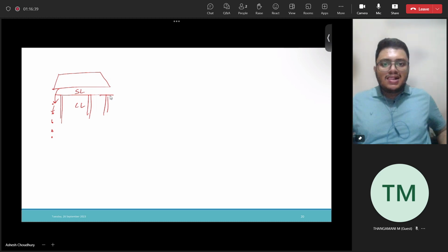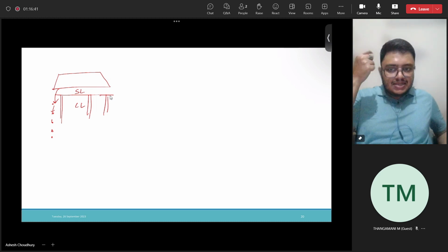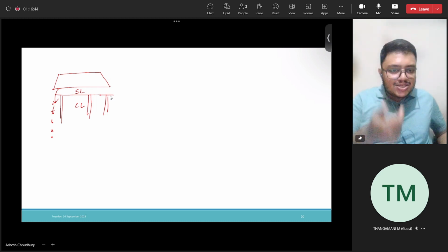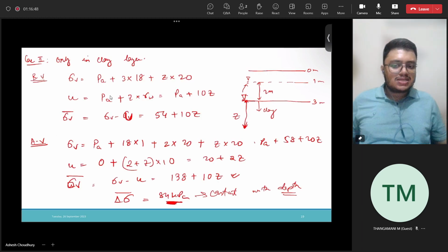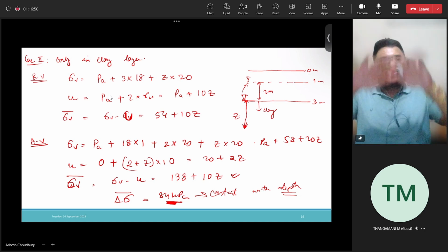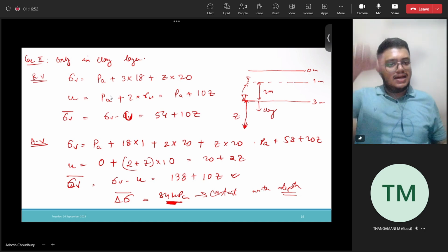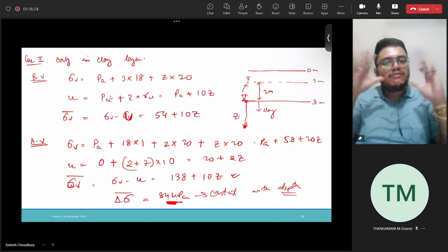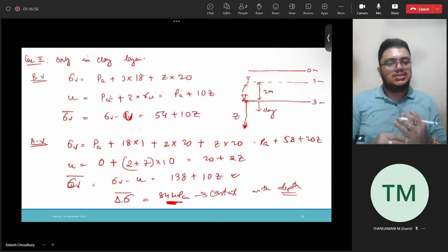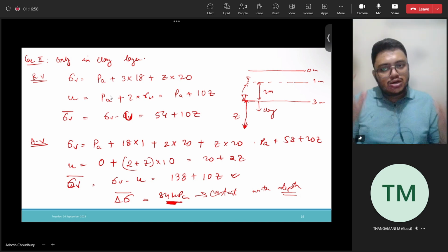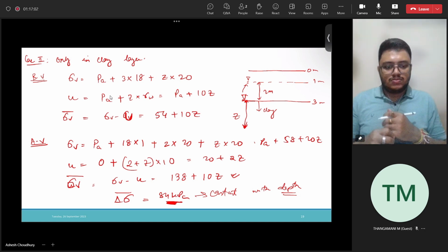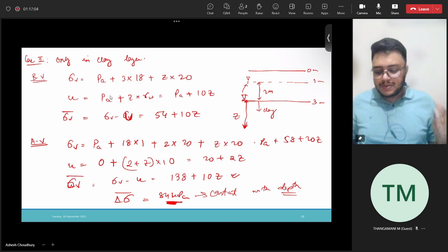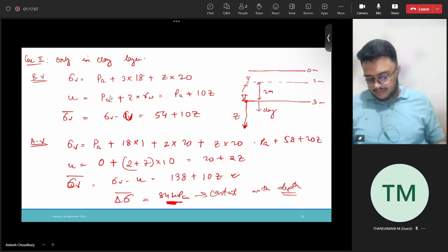What happens? At all depths, the increase in effective stress is independent of depth. So you saw here, the increase in effective stress becomes independent of depth. So at all depths in the clay layer, you have uniform increase in effective stress, as a result of which the consolidation is also uniform and faster also. Alright, so that is the main benefit of this vacuum pressure.